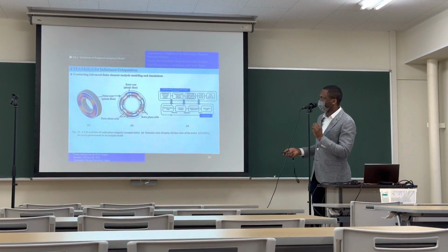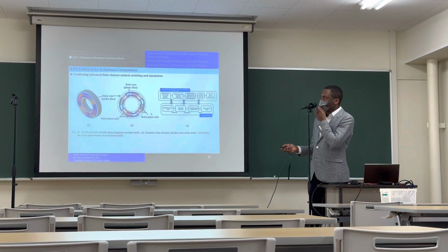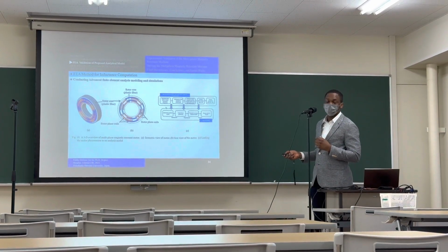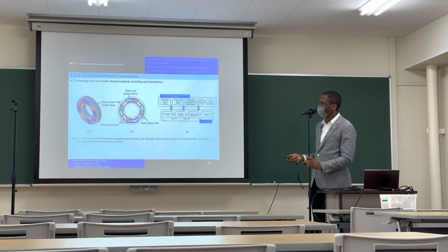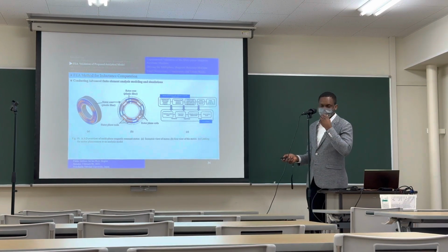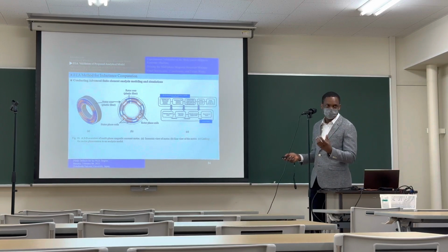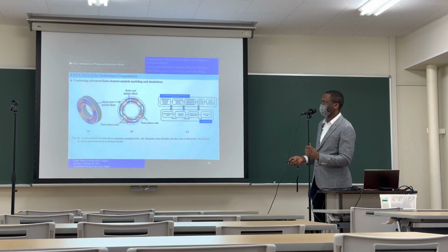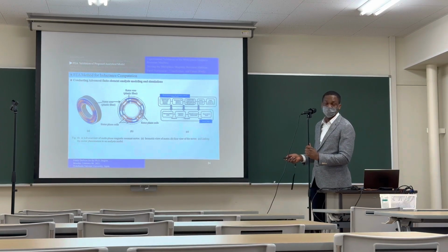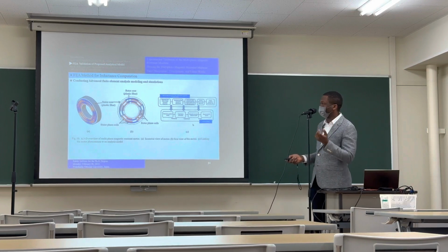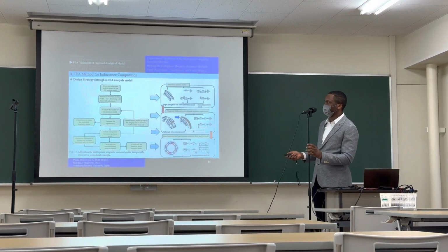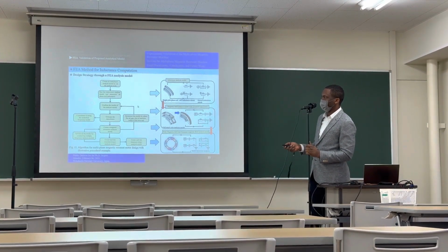The physical phenomenon in the machine is that we know there's going to be resonance because of the inductance. So we first create an inductance model. With that inductance model, we use the model of the machine and determine the inductance of the machine through finite element analysis. Then we decide the capacitance and run a magnetic resonance analysis, still with the model of the machine. And then we can do torque analysis, all of this with finite element analysis. So the procedure is quite elaborate here.